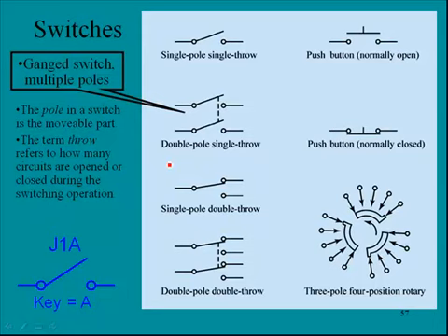In this case there is one circuit here, and it is either energized or de-energized, hence the term single throw. Now in this particular one, each of these dots indicates a different circuit. So this particular pole could activate one of two circuits. So it's a single pole, one movement, but double throw in that it can control two different circuits. And here is a double pole, single throw. Now here's an interesting one. Here is a double pole, double throw.